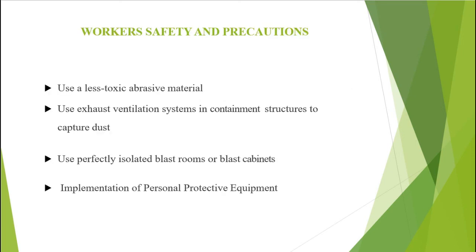Worker safety and precautions. Use a less toxic abrasive material. Use an exhaust ventilation system in the containment structure to capture the dust. Use perfectly isolated blast rooms or blast cabinets. Implement personal protective equipment.